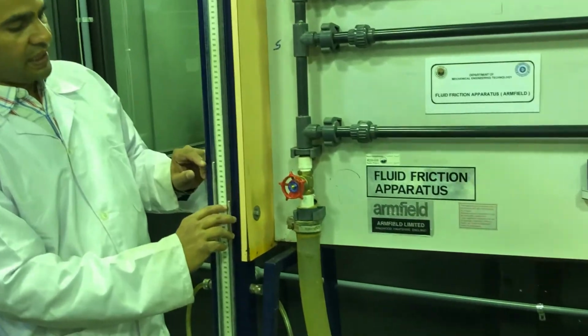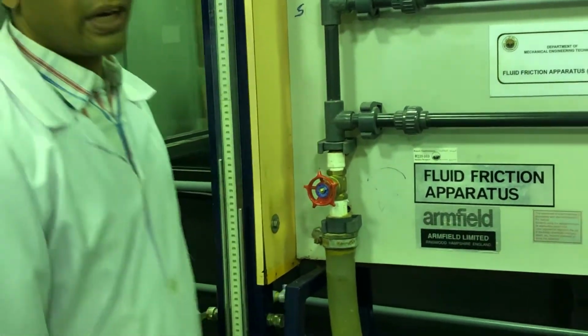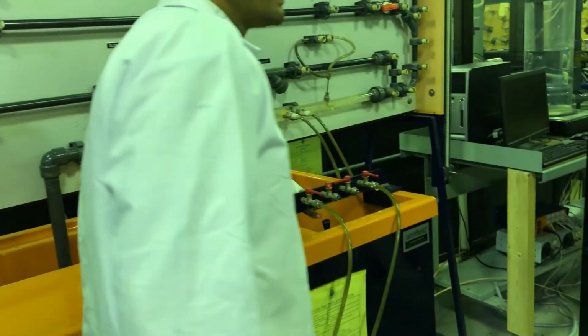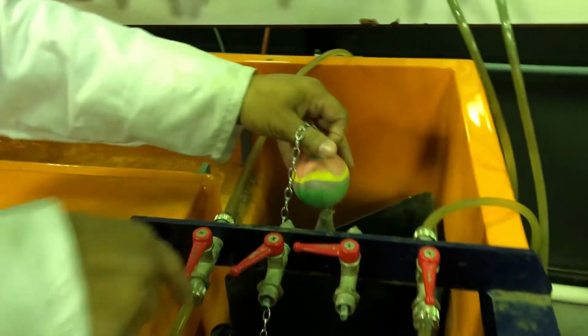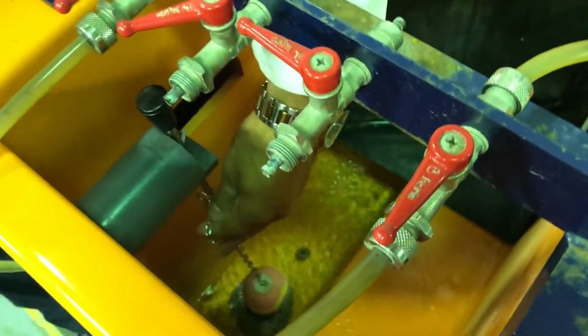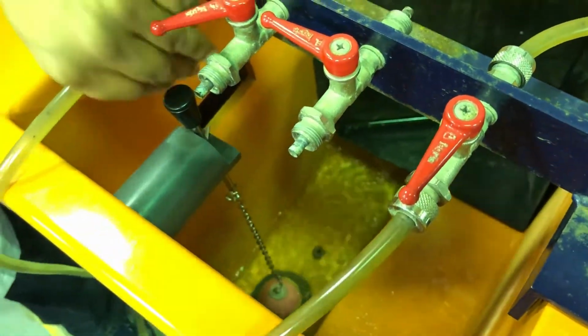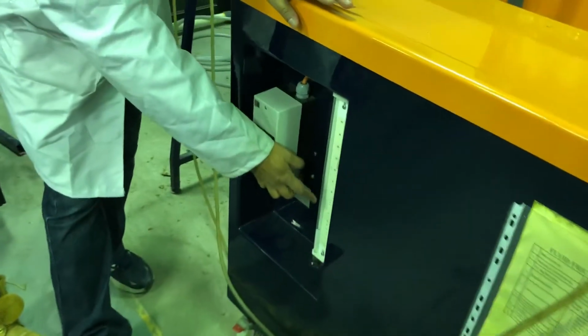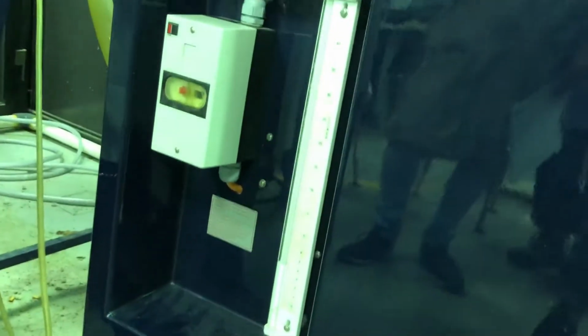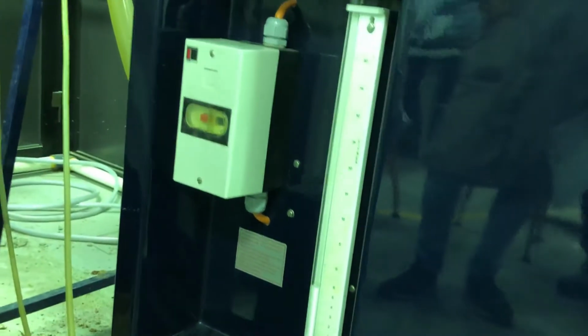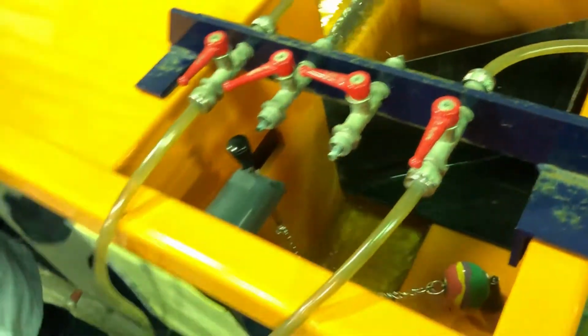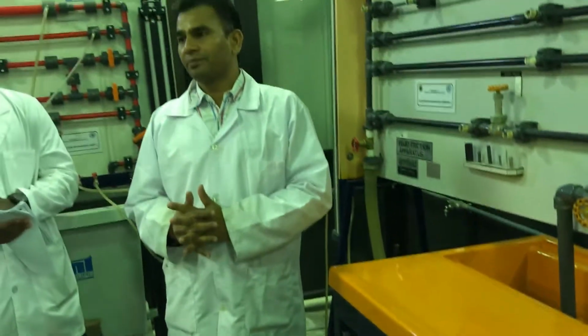Now we record the readings H1 and H2. We'll collect water in this tank for 10 liters. You can see this valve. We can close this valve with the ball, and we can measure the time from 0 to 10. So to collect 10 liters of water, measure the time. When the water reaches above 10, remove this immediately. Okay?